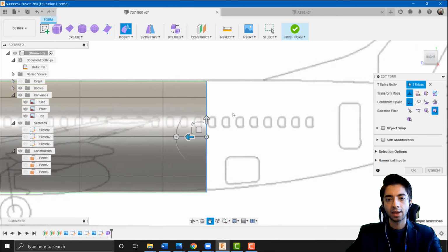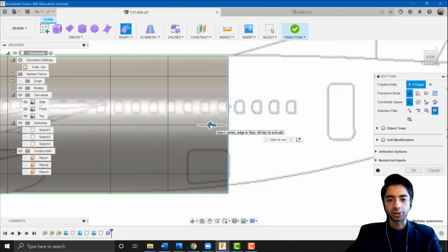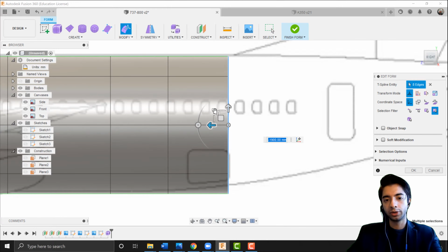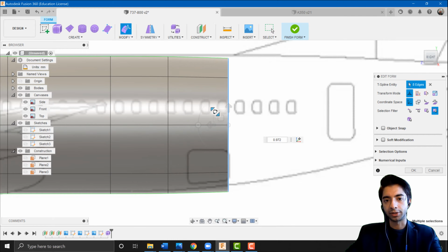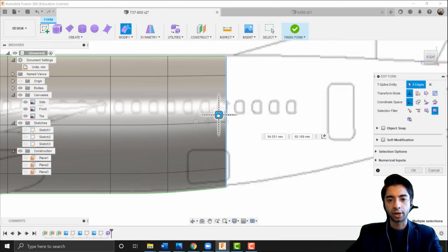and it does. Okay, so every time we extrude, we fix the extrusion on the right-hand side, and then we fix the extrusion on the top side, and then we extrude again. So extrude again, and maybe I'll stop it somewhere here. In this case, we're going to click on this one and just scale it in 2 dimensions. The reason why we want to do this in 2 dimensions will make sense in a bit. Once you've done that, you can then use the middle one and readjust to make sure that the curvature is still intact.